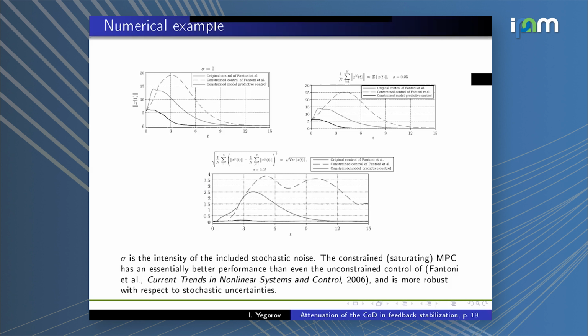So there are certain analytical expressions that give us the control. Also, those analytical controllers are not constrained. So these are just some expressions. And of course, if we have certain constraints on the magnitude of our controls, they may not be satisfied if we are sufficiently far away from the origin.